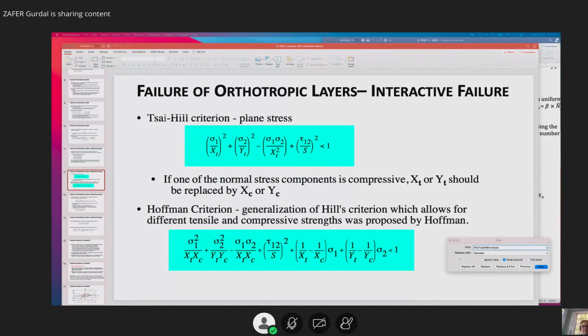Otherwise, you would not design a laminate like this, where if M is equal to 3 or 5, you don't put all 5 next to one another. But for the A matrix, it makes absolutely no difference. But for the D matrix, it makes a big difference. In which case, the relative distribution of each of those layers is a whole lot more complicated than just lumping everything together like this. So this is, in fact, one of the things that I'm thinking.